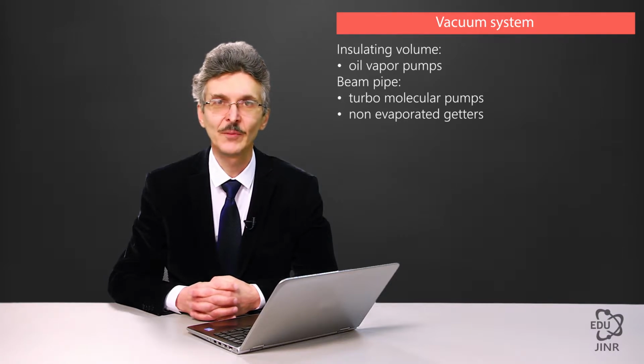Accordingly, they measure the pressure not in the beam chamber itself, but in the pipe connected to the beam chamber, located quite far from the chamber. It's not always easy to recalculate the pressure indicated by a vacuum gauge into the residual gas pressure in the beam chamber.